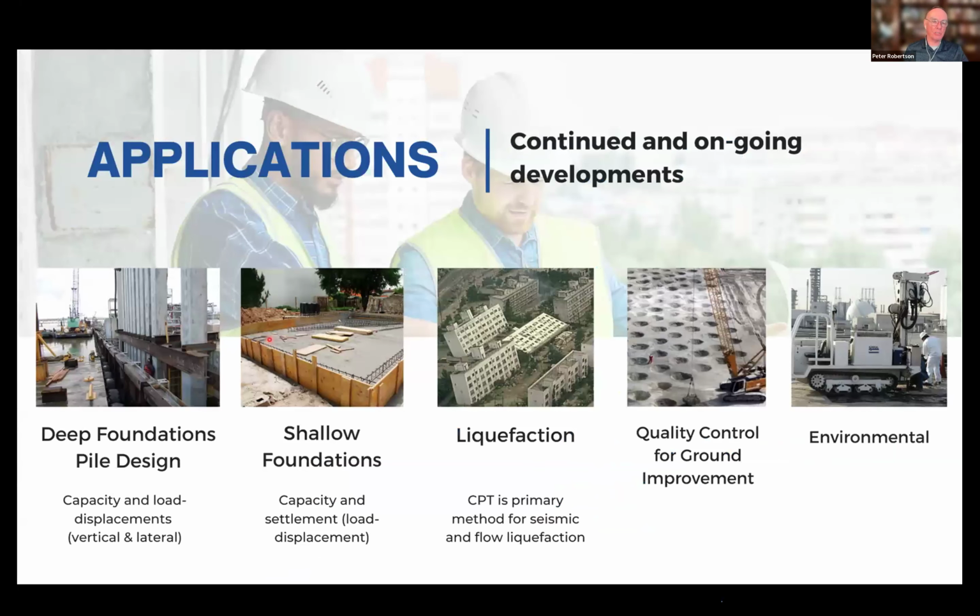When it comes to applications, in the early days, a lot of it was deep foundation, pile design. Then shallow foundations became popular, estimating the bearing capacity and settlement. Of course, liquefaction analysis. In the mid 1990s, we developed a method to estimate the liquefaction triggering, and over the years, it's developed. And so we actually developed a sister program called CLIQ, which is a CPT-based liquefaction program that allows you to do detailed liquefaction analysis.